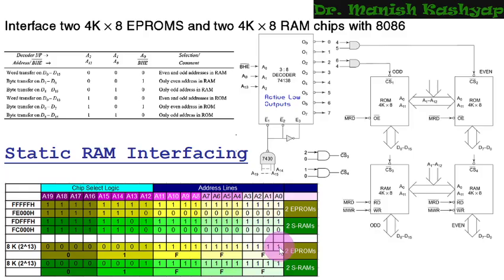You start from bit number 0 and go to bit number 12. So these many bits will be 1, rest everything will be 0. And if you convert this into the hexadecimal number, the first 4 bits are all 0, so this is 0. The second are 0001, so this is 1. Similarly, this is F, F and F, right? So the hexadecimal number for 8K is 01FFF.